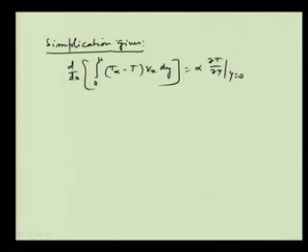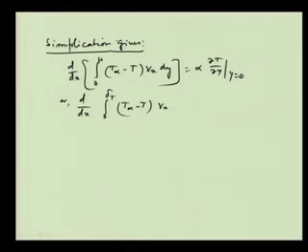Now, here should I put delta or delta t? I should put delta t, because h would be replaced by delta t. That means d/dx of the integral from 0 to delta t of (T infinity minus T) V x dy is equal to alpha into del T by del y at y equals 0.